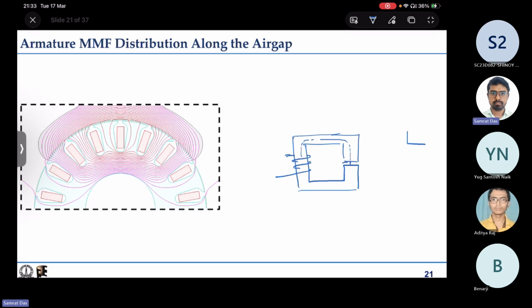In case the gap is quite big, say as big as this, then it is not possible to just calculate the reluctance by assuming some flux path like this and calculate B. It will be quite erroneous. You have to always keep in mind that our magnetic circuit approximations hold good only in cases where there is a very small air gap in the flux path.